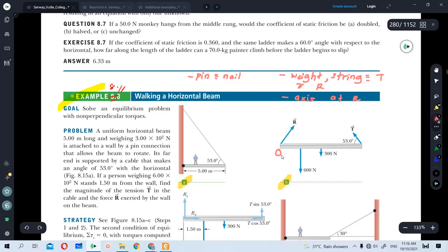And because it's at the pin position, let's now determine the direction of torque. Direction of torque for H1. You will find that torque given by R would be 0 because the R distance or lever arm is equivalent to 0. So we can neglect the torque from the R force. In the case of tension, the torque would be in this direction, counterclockwise, or you find that your thumb is directed out of the page.